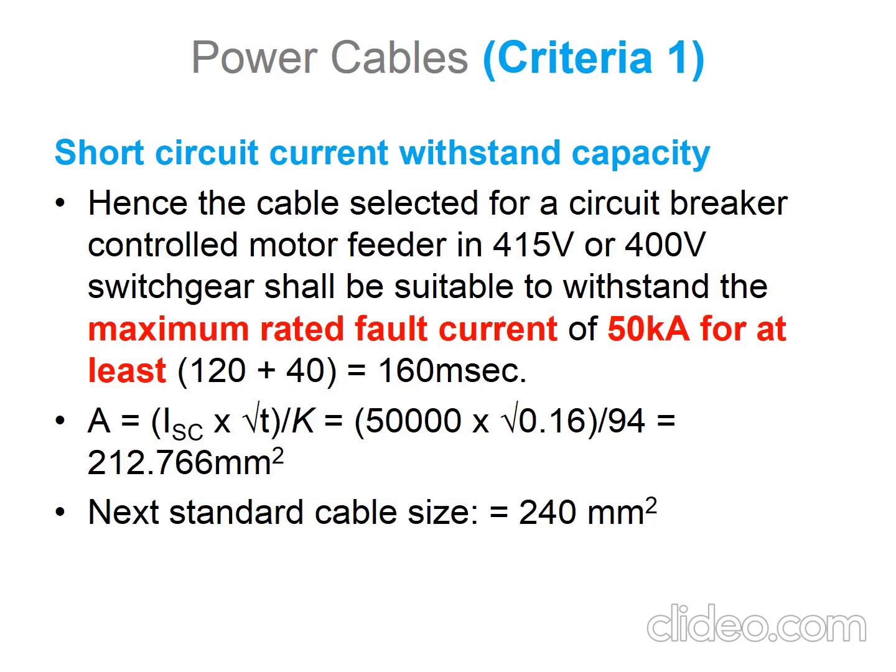Hence the cable shall withstand the maximum rated fault of 50 kA for at least 120 plus 40 millisecond, which is equal to 160 millisecond. So we can calculate what is the A by using equation number 1.